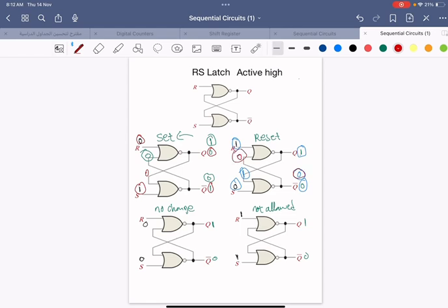0 and 1 is going to give me 0. So again, this 0 is here. We'll try one more. 0 here with the 0 is going to give me a new value of 1. This value, which is 1, is here. With 1 is going to give me 0. Then because of 0 here at the Q and 1 at the Q dash, we call this operation a reset.